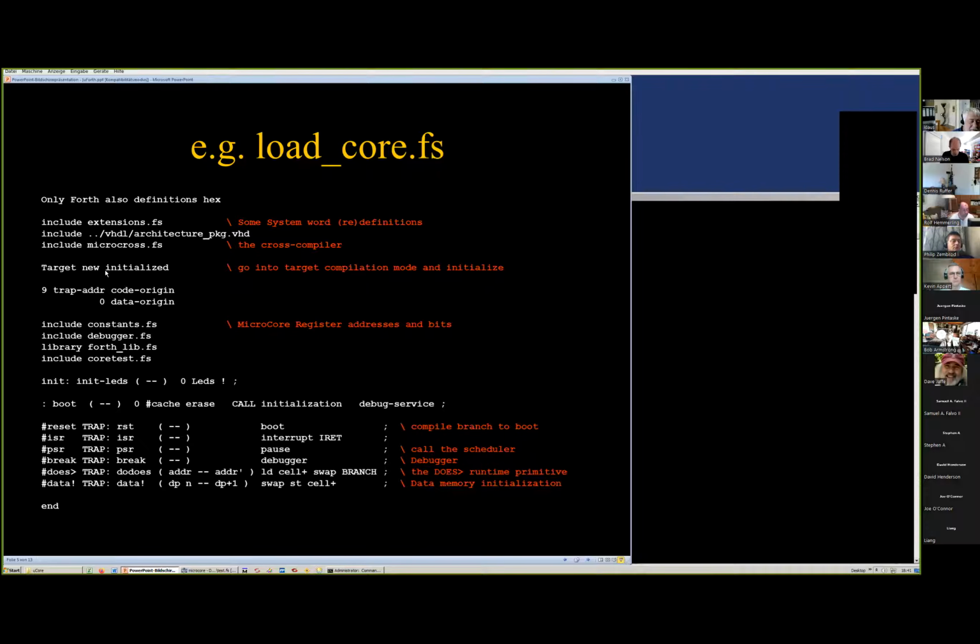And then there is this strange word, initialized. I have two operators, initialized and uninitialized, in order to control which interactive variable assignments and creates with commas after them will be automatically included in the boot code and will eventually initialize the data memory to the state which I defined interactively while preparing the source code.